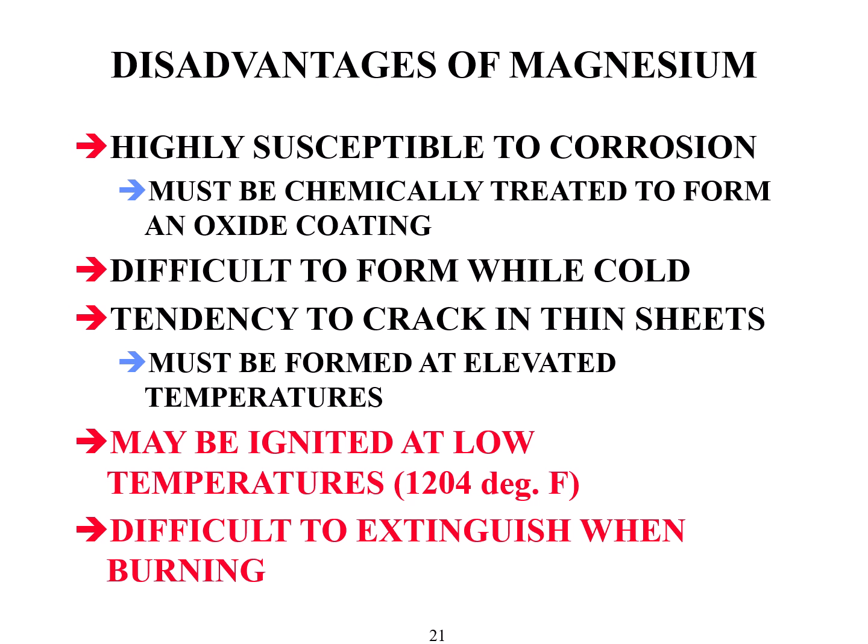So often these thin magnesium parts are formed under temperature and pressure. Thin sheets will crack, and if you ignite magnesium, and I've learned this one through pure experience, it burns very hot, and water will not put it out.